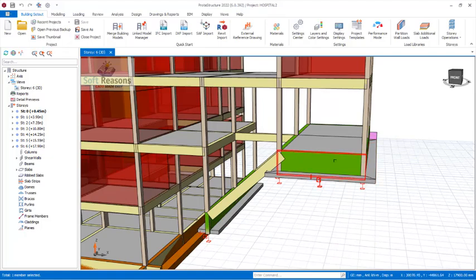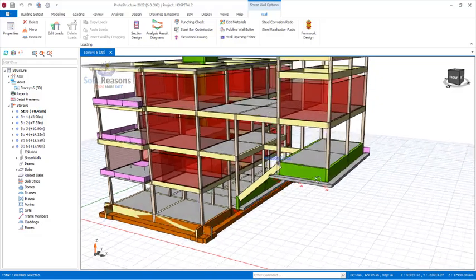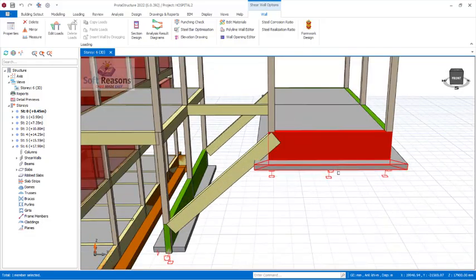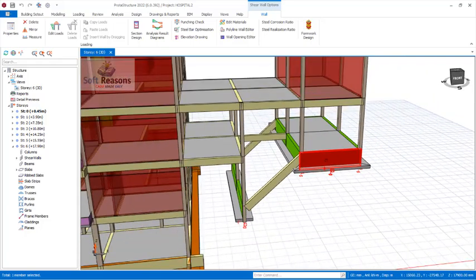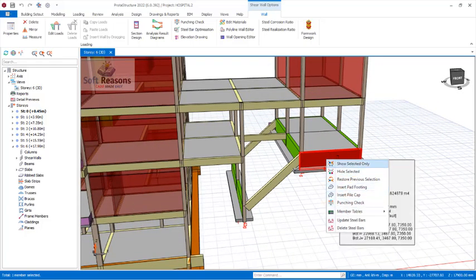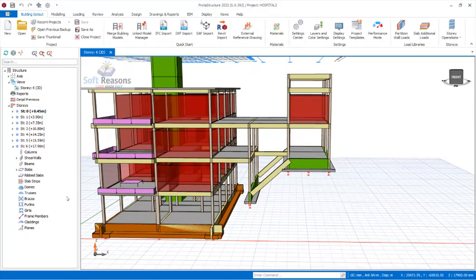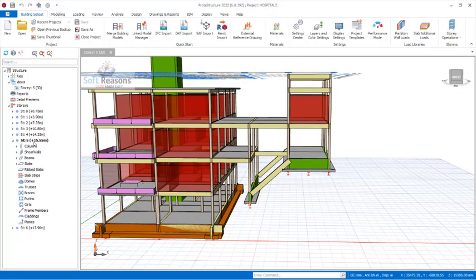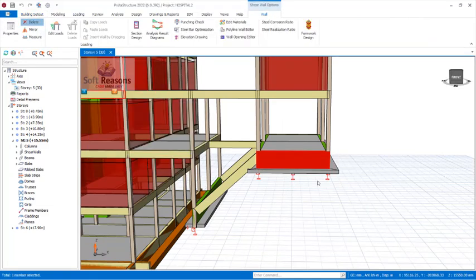So I will get rid of this. This is the shear wall. Actually, this is the shear wall. I will show you how you can apply a fixed support to this shear wall to be able to anchor it at this foundation level. I will delete this shear wall at first, so I will select it. By then I will move my grid lines from the level where it is to maybe level 6 right there, or level 5, and then I can get this selected over here. I can see delete. I can get rid of that shear wall as I get it deleted successfully.